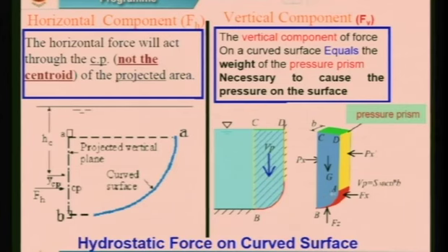Now you may be thinking, okay sir, we got only the area, not the volume. My dear students, gamma W, which is 9810 for water, into area, I will take area of a quarter circle plus the area of a rectangle. Rectangle will be from here to here. So this width into this depth I will calculate, and you may be thinking what will be the length?